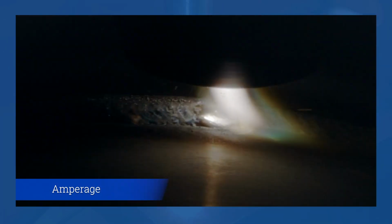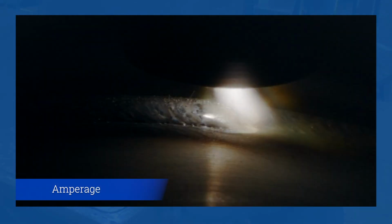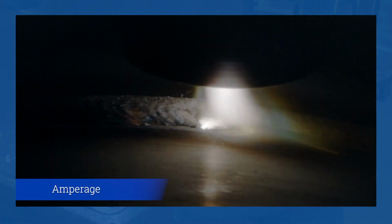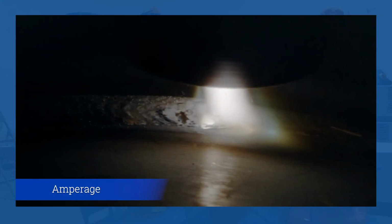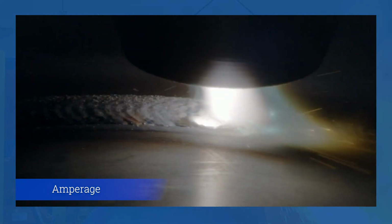Now we're down to too low an amperage, and this is pretty obvious in the edge of the weld. You can tell it because it's not wetting and flowing. It's not working very well at all. You're not getting good fusion. And then we'll turn it back up. Now we're back at correct amperage. For this situation, it's 100 amps. It looks pretty good. This is a key variable you must learn to control.